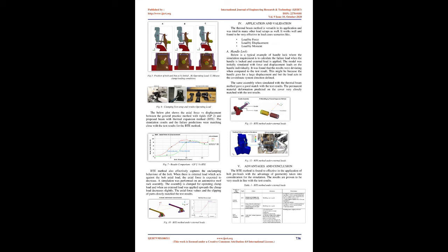The below plot shows the axial force vs displacement between the general practice method with rigids, GP2, and the proposed beam with thermal expansion method, BTE. The simulation results and the failure predictions matched closely with the test results for the BTE method. BTE method also effectively captures the unclamping behavior of the bolt.